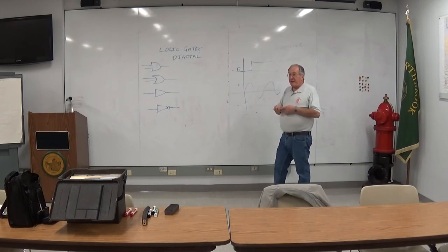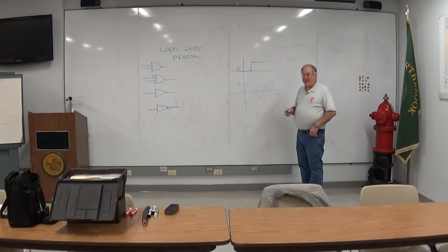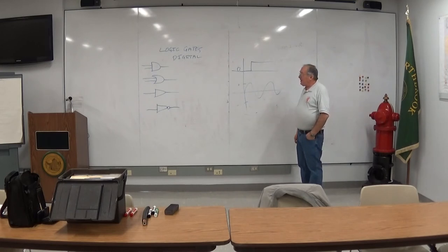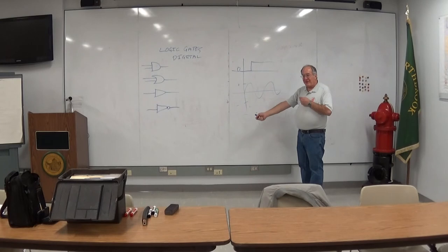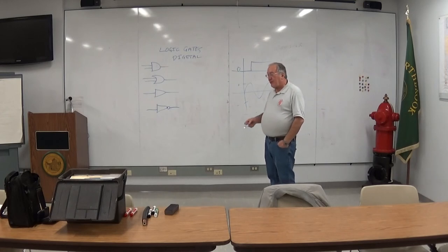And indeed, that actually happens in a framework called RS-232. You may have heard of that in the old days as one of those interfaces used to put your serial device on your computer. And you deal with things like baud rates and parity, and whether you use a 25-pin connector, which only had 3 active pins, by the way, or the newer one, the 9-pin connector.